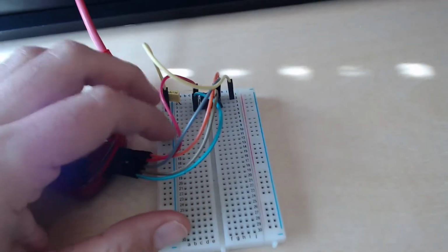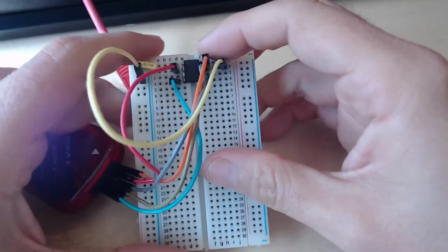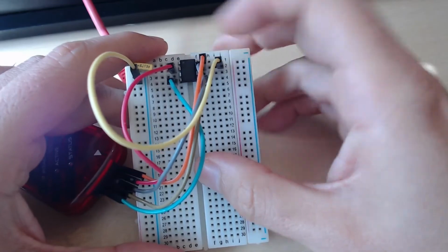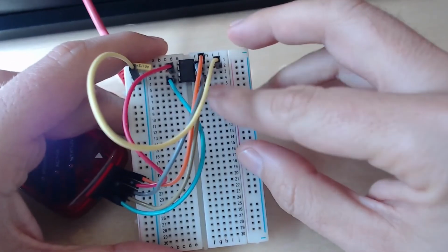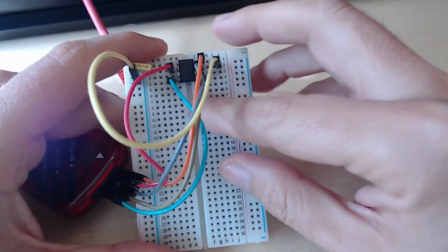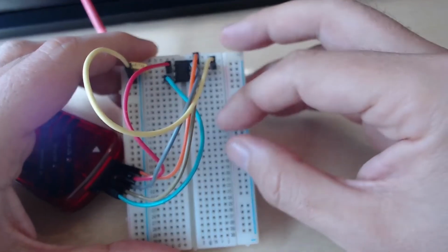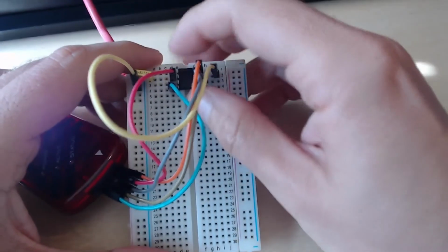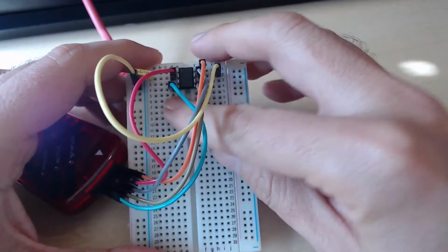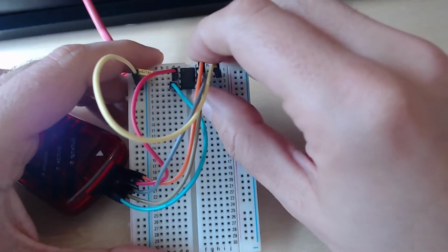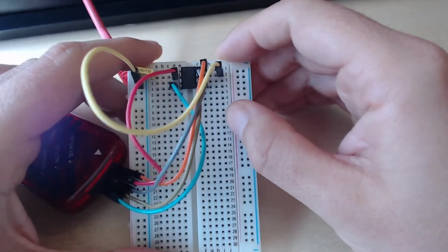Another issue that could happen on the board is if you have an external circuit, external components connected to MCLR and the data and clock pins. They might cause trouble because they might disrupt the communication between the PICKIT3 and your micro. So just remove all of them if you want to simplify things and get to the bottom of the issue. Make sure that nothing is connected to the ICSP data and clock, and that your MCLR can be driven high and low without the impact of any external components.